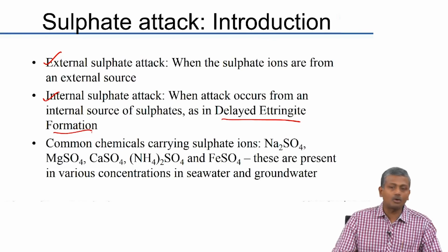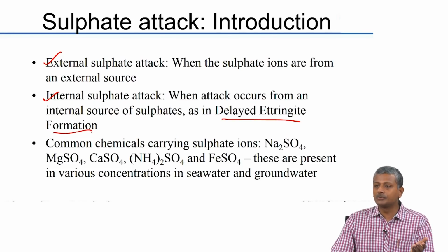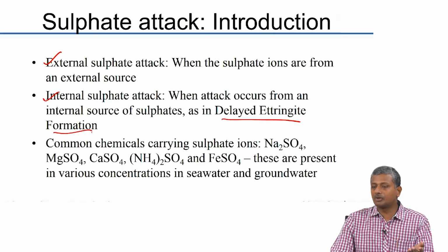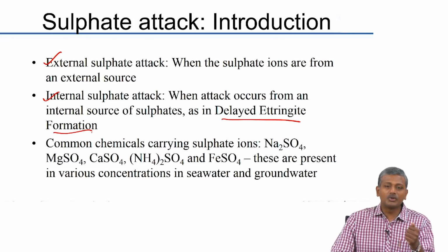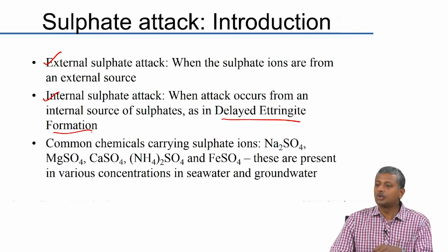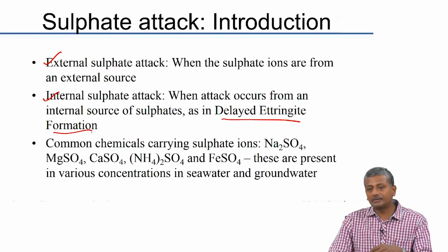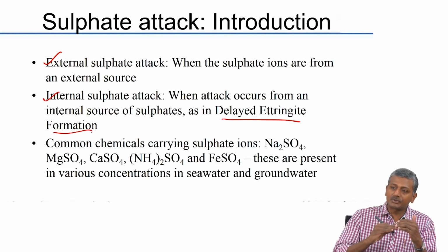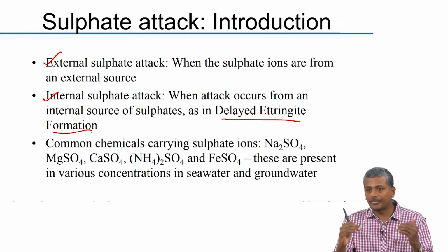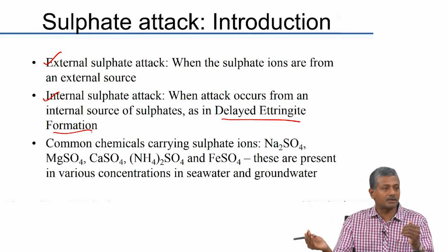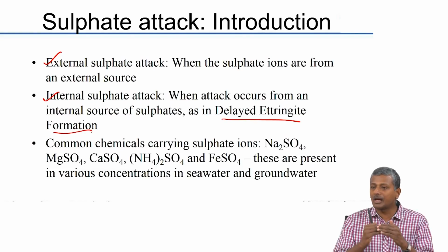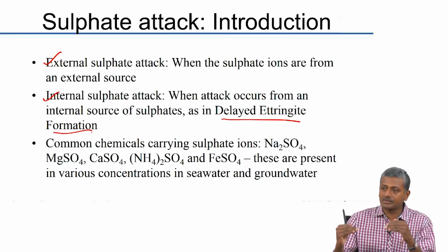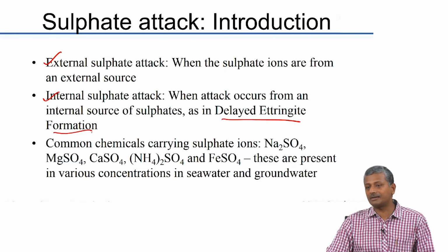In normal sulfate attack also this ettringite formation happens in the hardened concrete, and to protect against that we use what? What type of cement do we use to protect against ettringite formation? Sulfate resistant cement, right. We use sulfate resistant cement which is low in C3A, tricalcium aluminate, because if you have more C3A, the tendency is to stabilize the formation of monosulfate. So, that monosulfate can reconvert to ettringite in the hardened concrete, but when you have low C3A, the tendency is to stabilize the ettringite at the early stages. So, you do not have formation of later ettringite.